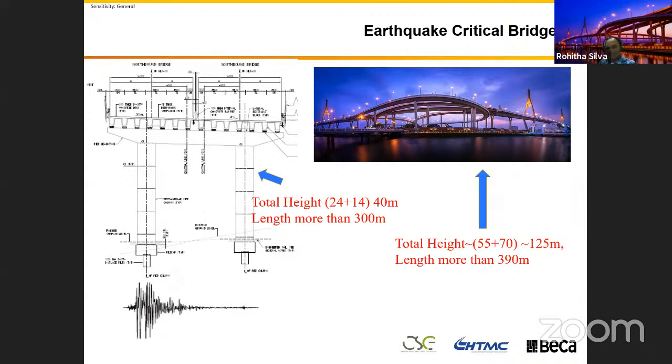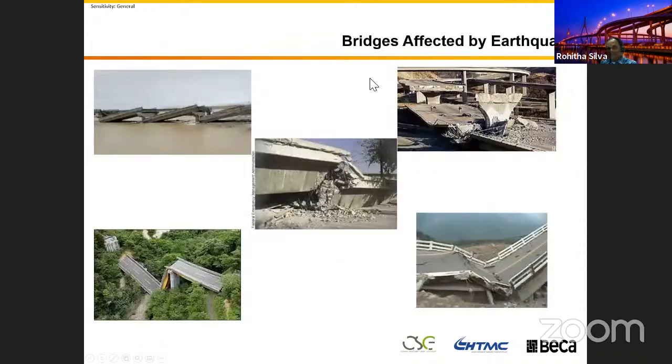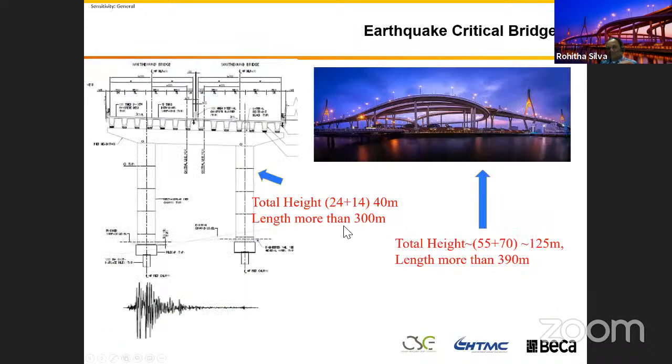For example, the primary load case we design bridges for may not be as significant as that, but we still detail the bridge to make sure it won't happen like this. Even during an earthquake, if a bridge's superstructure slips, it is not a collapse. But for you to go back and jack this bridge to its position, it's really difficult.